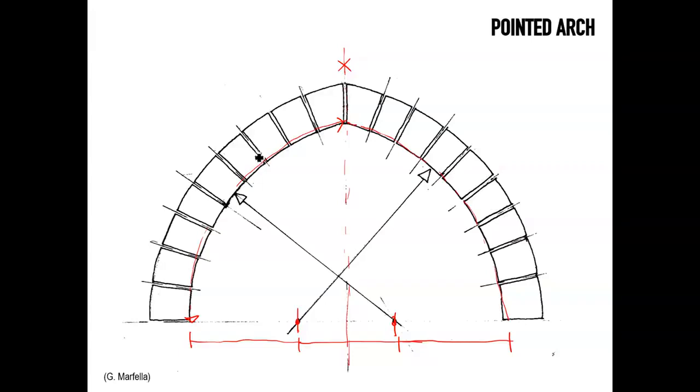But what is it really that makes it work more desirably than anything else? It is the fact that this configuration, in a certain sense, acknowledges that there is a point of rotation there. The two arches are not necessarily supporting one another. You would imagine this arch with a tendency to rotate here from left to right, but the other side of the arch would tend to do the same. So the two arches are almost supporting each other at the key, number one.